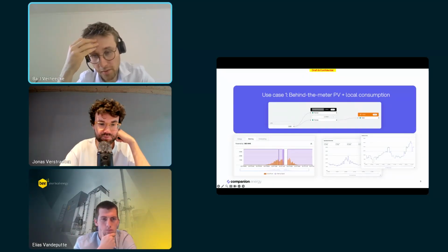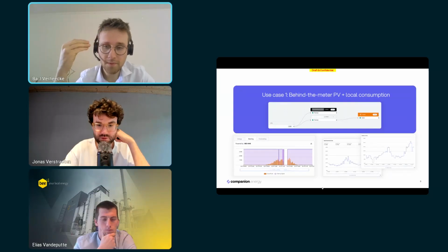Yeah, and in some of the cases, you're good to go with just connecting the EMS to the local network, and then over Modbus TCP, which is one of the most common communication interfaces, it can work straight away. Though one of the first things where you need an installer is opening up this communication on each inverter.